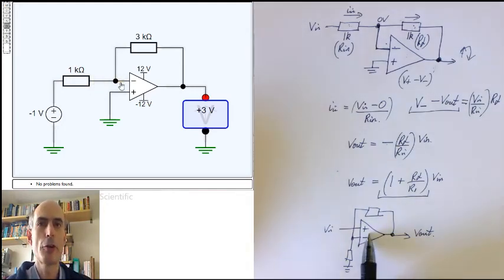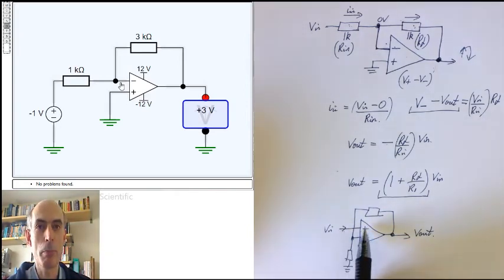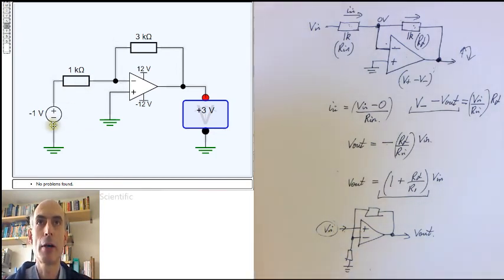The non-inverting amplifier doesn't. For an ideal op-amp, there is no current flowing into the inputs of the op-amp, so no current is required to flow out of our voltage source, whatever is providing V in. For the inverting amplifier, that's not true, and current is having to flow out of our voltage source here. In the case where our voltage source has a Thevenin resistance, which is of a significant value, that's an important point to keep in mind.